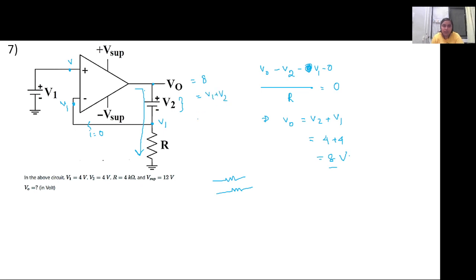So this is kind of an adder circuit, but actually it is not a straightforward adder circuit. This V2 input voltage is connected in the form of a feedback. It is replicating an adder circuit. Whichever configuration the circuit is connected in, the amplifier, it's not necessary that it be like the adder circuit that sir had shown, if you remember, where there were two input terminals connected to the inverting terminal of the input. That is how the adder circuit was shown. This is just to show that there might be different configurations in the circuits.